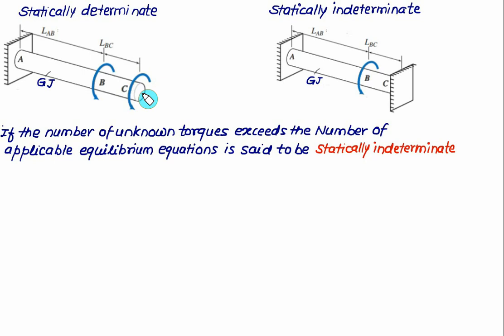If the shaft has one end free and one end fixed, then it is called statically determinate. Otherwise, if the ends are free, just by looking at a figure you can conclude that it is statically determinate, and one simple equation, that the total sum of the torque must equal 0 for each section, lets you draw the torque diagram and solve the problem.